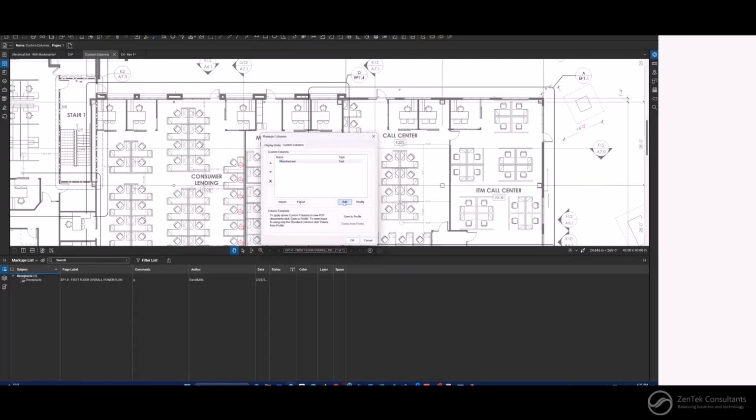And then we're going to do add again. Talk about number. Number allows you to only enter a number. So we have normal, currency, and percentage. Again, we want to put in, let's say, a cost. So instead of having normal here, we want to change this to currency. And depending on how many decimal places you want, I'll keep it at 2 decimal places, and for the currency, I'll keep it as dollar.